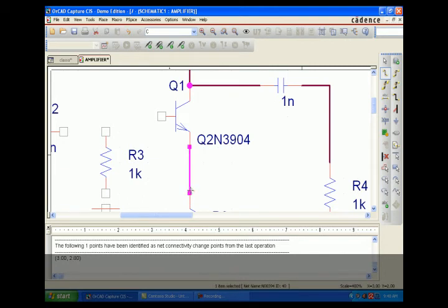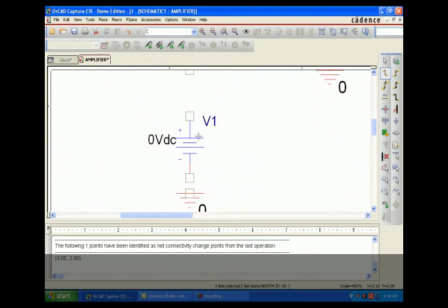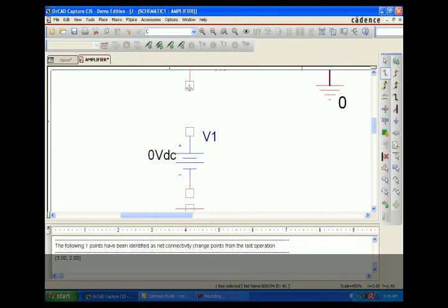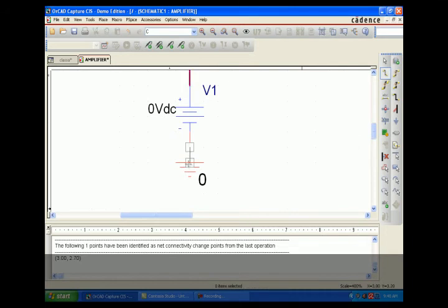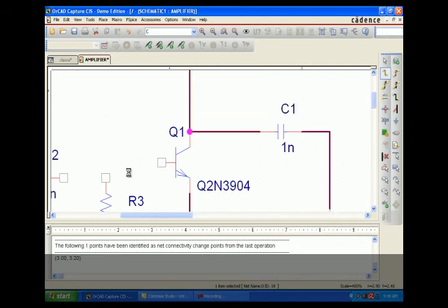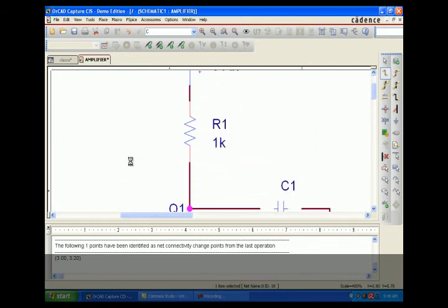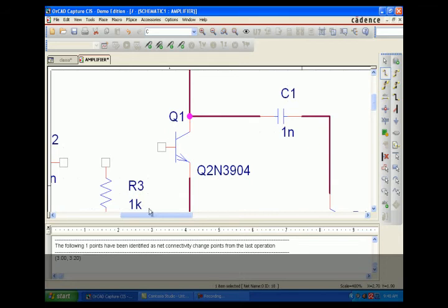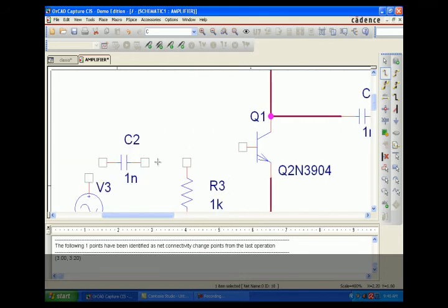Here we have used a simple and stable emitter biasing because we want to design an application for the maximum possible unclipped output voltage, and we must be able to handle the heat dissipated in the transistor. So using a simple emitter configuration with a very small value of resistance, we can use it for high voltage and current amplification.